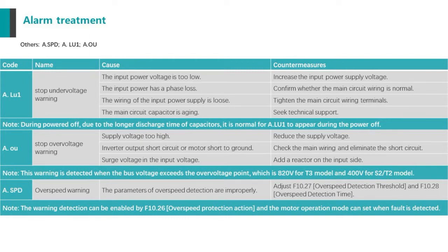This is actually due to the high voltage configuration as well. When the bus voltage is too high, the inverter will try to increase the running frequency to consume the DC bus voltage and DC power. If this condition lasts for the protection time, this alarm will occur.